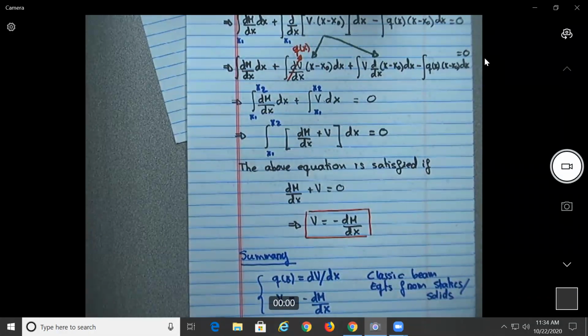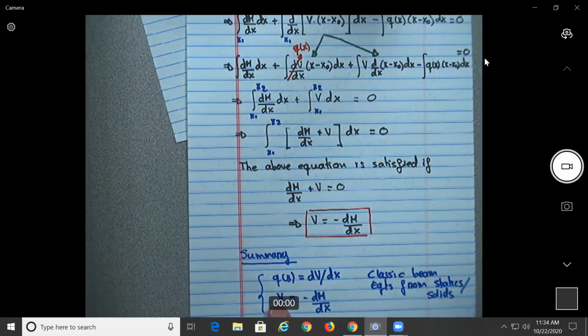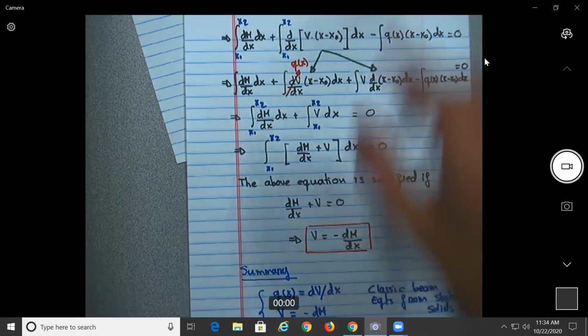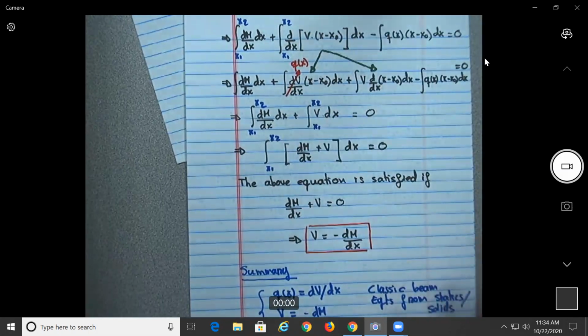Okay, personally, I know that was a long time ago for you, no statics. But if you ask me what is the most difficult part in statics, is this: how to do those shear and bending moment diagrams. If you have a straight line, it becomes a quadratic. Really what you have to do, if you know the distributed load, you needed to integrate in order to find the V. And once you knew the V, you needed to integrate the shear force in order to find the moment. That was really the way to do it. Okay, and then we integrate, and by integration you end up with some constants of integration, and then you solve the constants depending on the boundary conditions of your beam. In this case, it's simply supported, no?